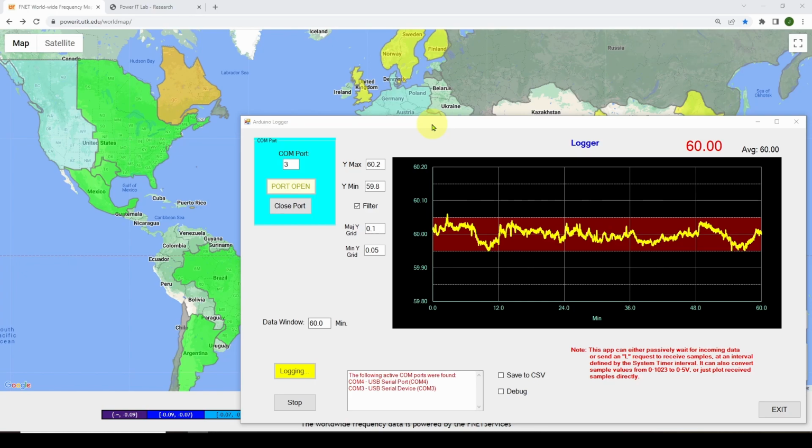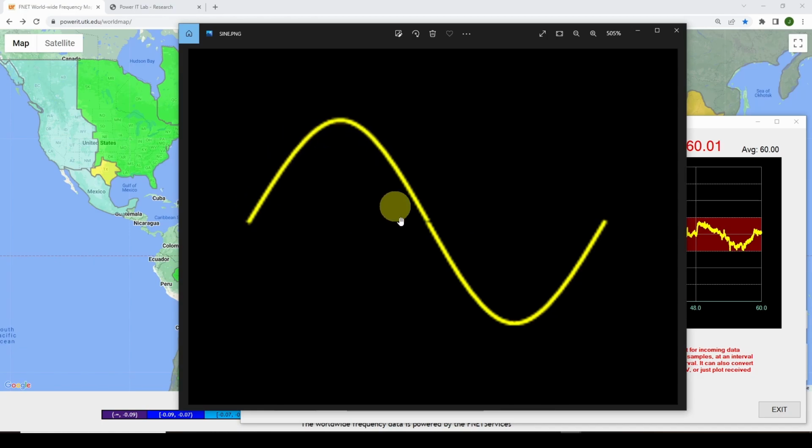If you know anything about frequency, you might think, well, what's there to know? You've got this sine wave, which represents the voltage at your wall outlet supplied to you by your power company. In the US, it goes 120 volts RMS, which means it goes up to a peak of about 170 volts and down to minus 170 volts. And frequency is just a measurement of how often that happens every second. Here in the US, it's 60 times per second, or 60 hertz.